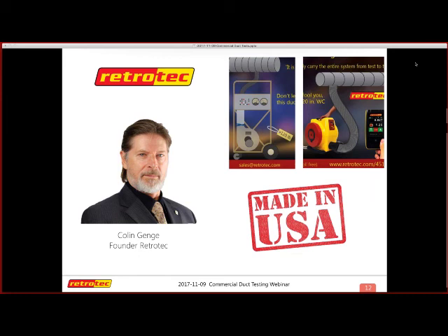Honestly, this is my opinion, and it's pretty common that most of the commercial duct testers on the market today are still following a 1960s, 70s concept: throw a bunch of air into something, use a calibrated orifice, use that orifice to calculate your results, and then determine what your leakage is. And it's a very cumbersome concept. There are some major advances in how that cumbersome technique is being automated, but in general, it still is a heavy, cumbersome device that still uses this orifice, and you still need to go to another place and confirm what your results are.